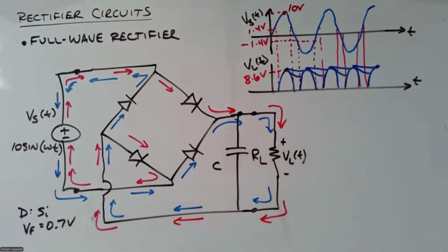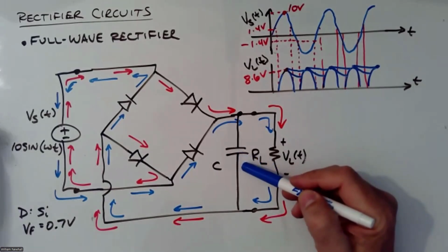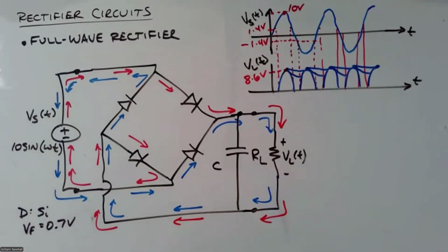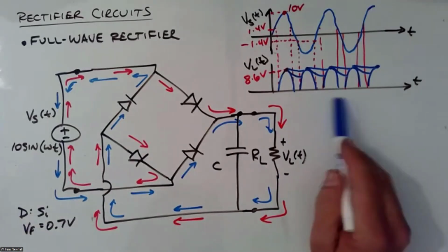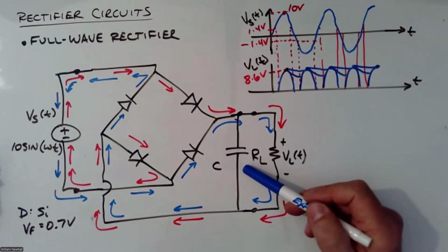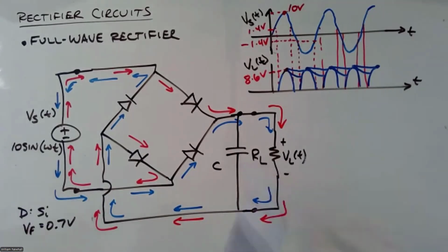And someone asks, can you make a capacitor have a value that's too large? Yeah, physically they get bigger. They get more expensive. They have different frequency characteristics if you're trying to do this with higher frequencies. So there are trades for when you make the capacitor larger.